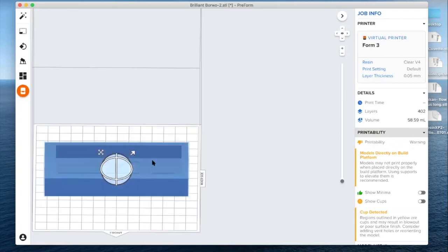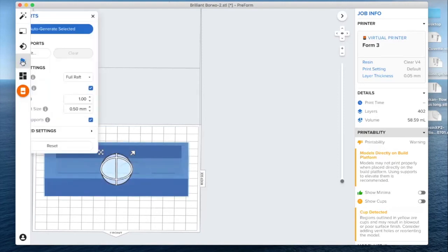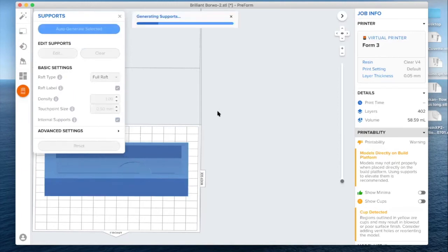But if you put it completely flat, you will not see the different layers. So you will see only the layer moving. This is why it's opaque. But this is the way to go if you want to print something flat. We again use the support, but practically that's it.